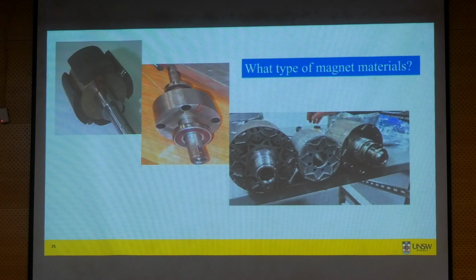And the third reason is also cooling. If you have these holes, they are air, so you can force air through those holes to cool the magnet. As I said, the temperature of the magnet is a very important point, so you want to cool the rotor as much as possible. Sometimes they do forced air cooling, or even forced liquid cooling. Some liquid could pass through. So there could be several reasons for this type of design.